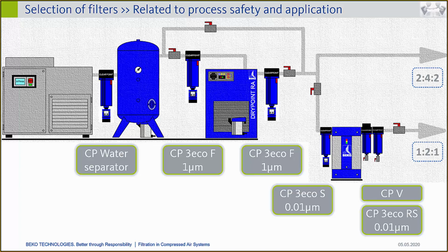The disadvantage is you may need reduction fittings. Any reduction fitting also needs space and has a potential for leakages, and so on and so on. So I would stay with the same size, if you have the required airflow to treat.